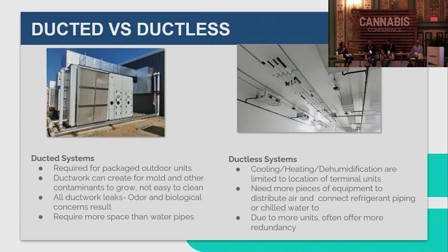Yeah, I think he covered it really well. The biggest complication of the ducted system is the exterior penetrations for the ductwork and the possibility of having contaminants coming in. That risk is there. But there's also benefits of you can have like a purge system running right through the unit, so it's less equipment that you have to put there, where we always recommend having some type of a purge ventilation system, even with a ductless system. So that would be a completely separate system, so it's a little added cost there.